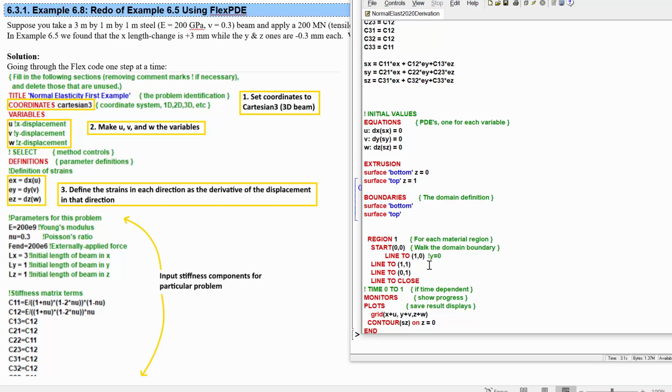The y equals 0 surface is the boundary condition we put right in front of this thing. And then the one in front of this thing would be x is equal to 1 and we're changing y. So this is the x equals 1 surface. And for this one, we're going to put a load in the x direction equal to 200E6. So 200 megapascals will be the stress that we have in the x direction. Yeah?